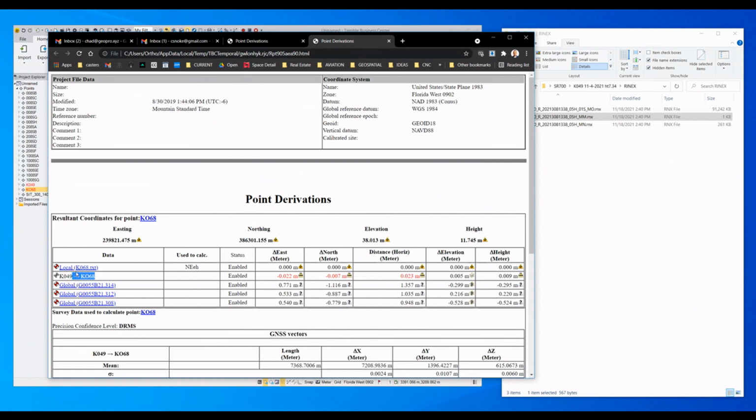Again, essentially what's going on between those 2 monuments, between what is published and what is observed, what was actually measured, there's a discrepancy. And that could happen for any number of reasons. One of those benchmarks could have been hit by a bulldozer or run over by a truck, and it just shifted things 2 centimeters in the easting and 2 centimeters in the northing. Oh, it's not even in the northing. The elevation looks good. So one of these monuments has shifted 2 centimeters, most likely.